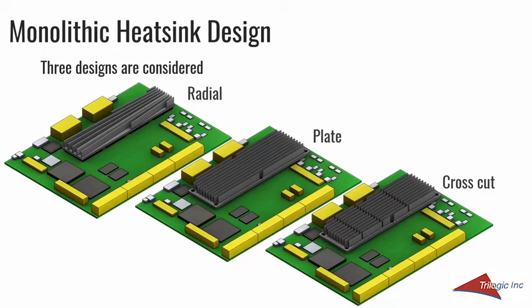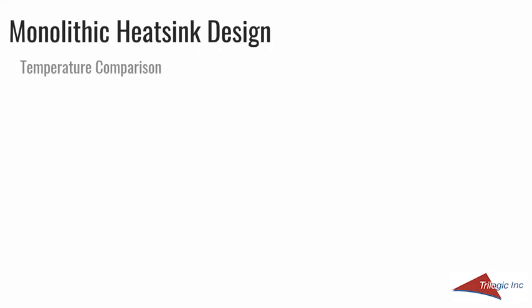So losing a little bit of surface area wasn't compensated for by any additional crosscuts. And that's what we said was generally true. When we're looking at these things, I want to see what I would call a sledgehammer. So if I see, say, a 1 degree difference in a 30-degree temperature rise, I'm not sure I'm going to spend a lot of time optimizing around that parameter. Anyway, that's my opinion. So anyway, these are 3 heat sinks we looked at.